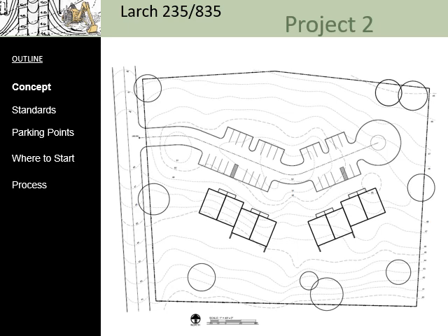So as we said, this is the basic site plan. You've got a roadway down the side, a parking lot, and some townhomes that you're going to have to make connections to. Your circulation for this is pretty simple. You're going to have folks that are going to drive in, park their cars, and then they have to be able to walk into these townhouse units. They also will be able to walk out the back of some of these units, perhaps not all of them, but it's important to note that you have a 9-foot difference in elevation between the front of the unit and the back of the unit. And again, we're going to talk about that again in a minute.